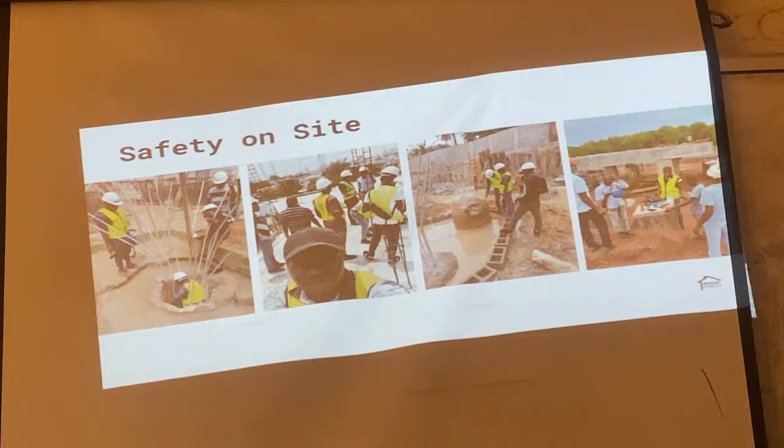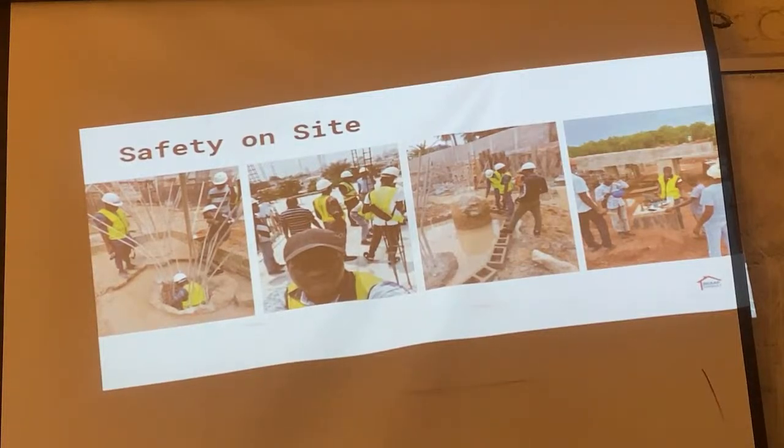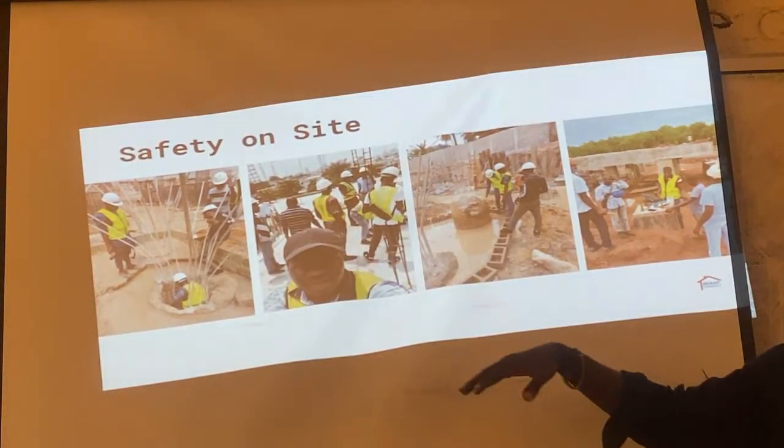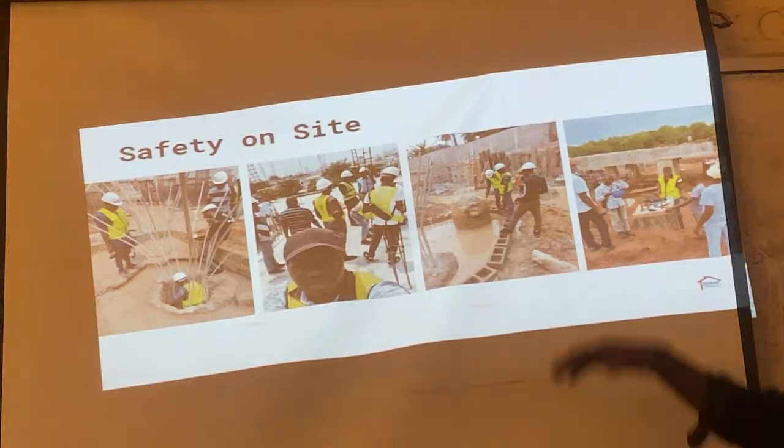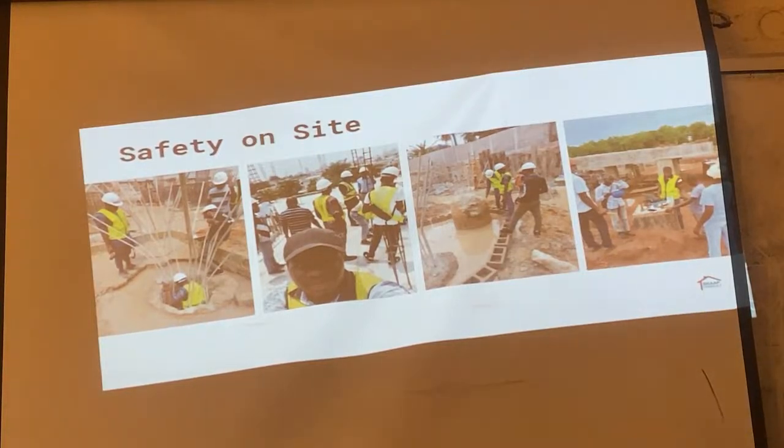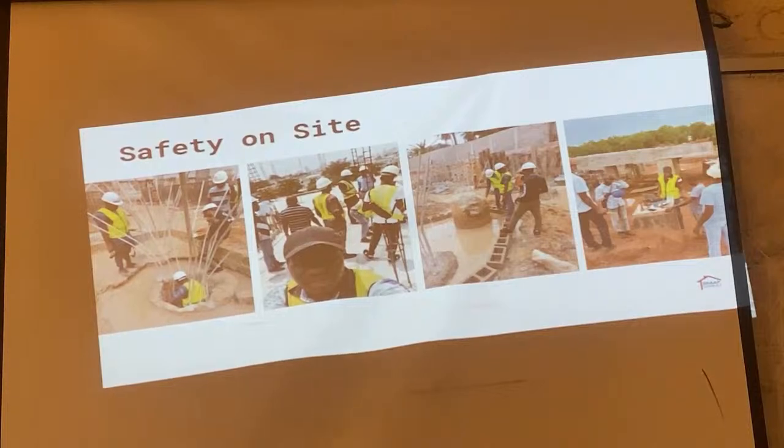No, you're not getting all the way to the depth of the pile. Sometimes it's just to test the pile cap at the stage. It's not that you want to get to the depth. When you get to the depth, you use pile load test.